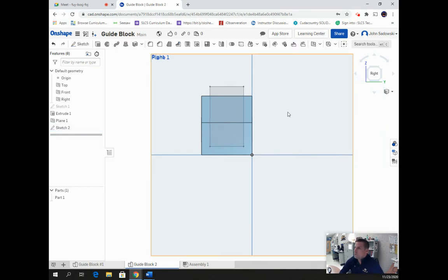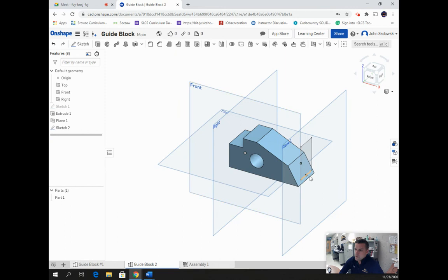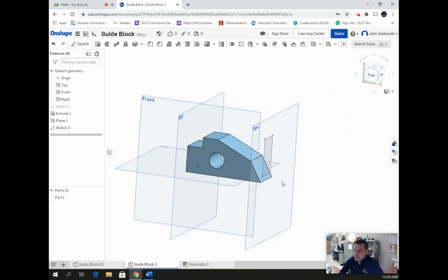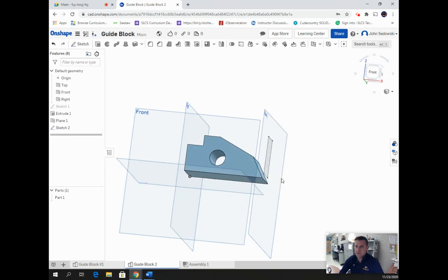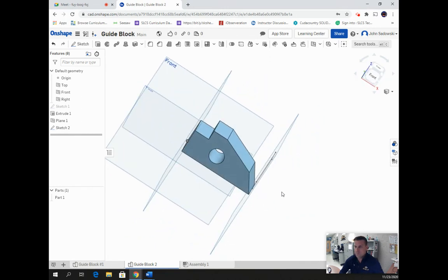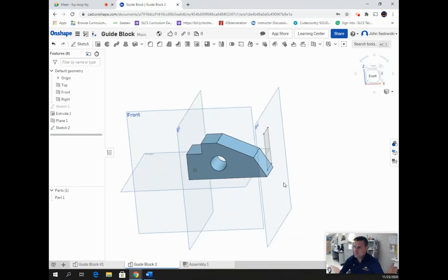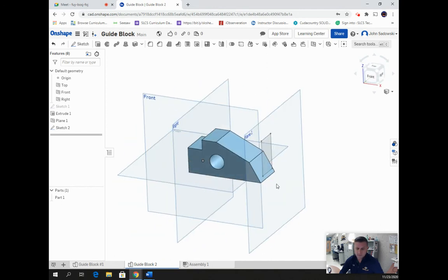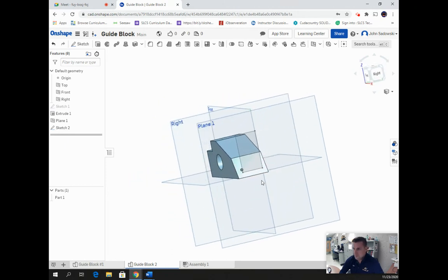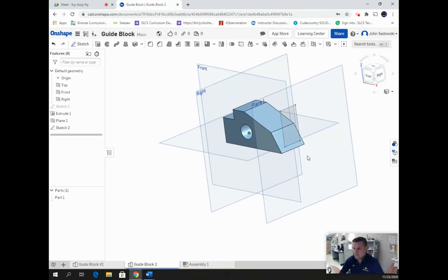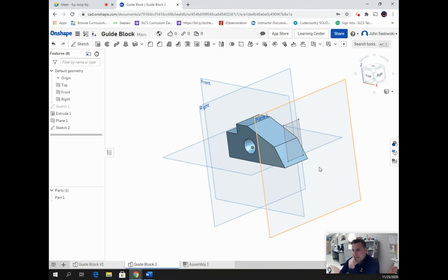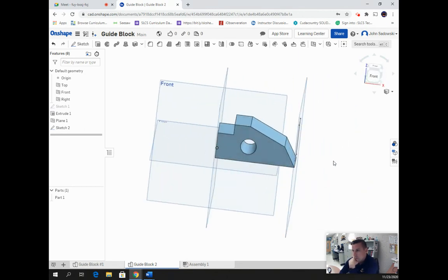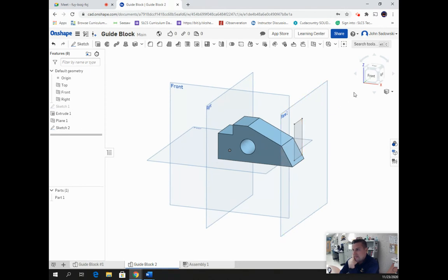All right, let's go back to this view here. You can see now it has that sketch on there. I'm right-clicking, for those of you that are brand new to Onshape. A little bit of differences from Inventor. I know in Inventor you have to right-click and hold Shift, so this is kind of a little bit better. Holding down the scroll wheel and moving around pans for you. So I want that sketch, and I want it to go back into this shape here.